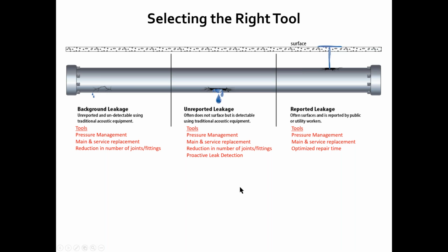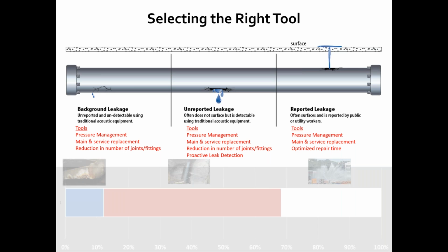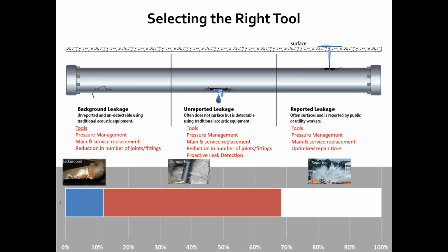And even in some situations with certain age and condition of infrastructure, most of the leakage actually might be in this background category and very little of it in the hidden or the stuff coming to the surface. And so in that scenario, the right approach is not going to be leak detection. It's going to be something else. So we'll give a couple illustrations here.